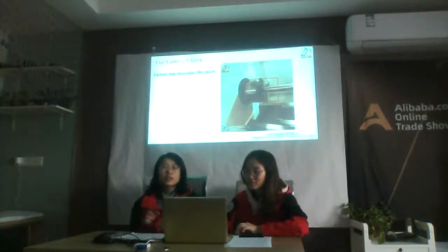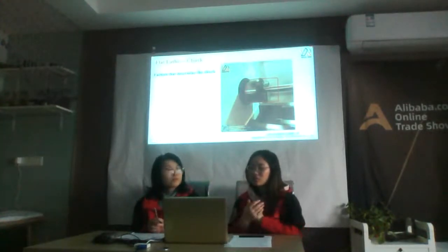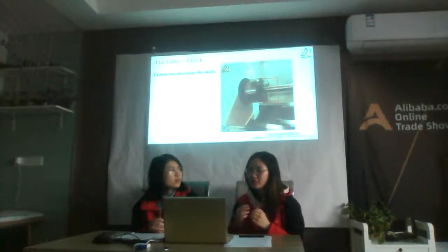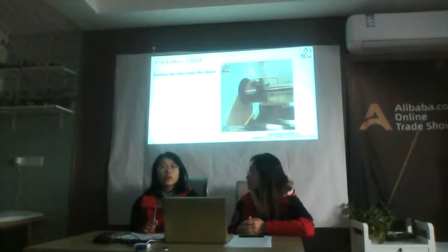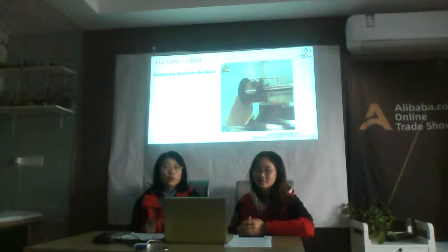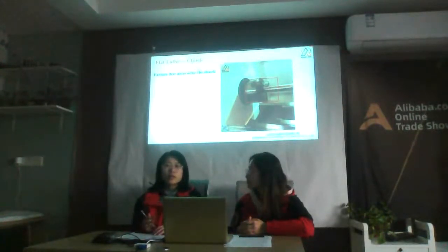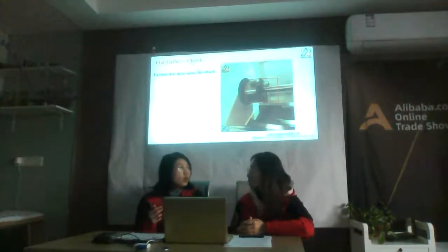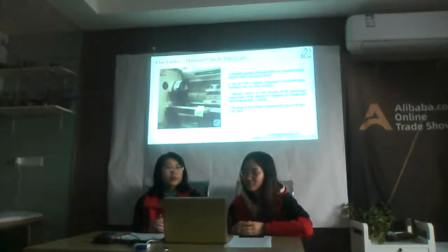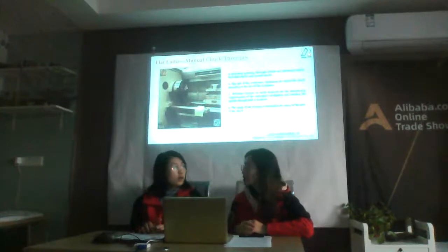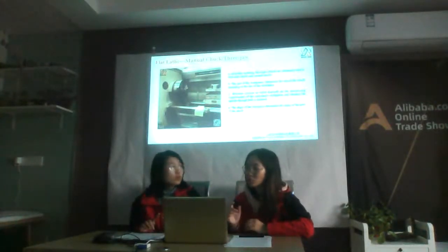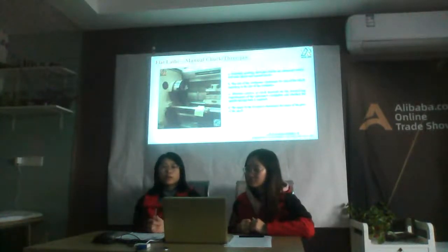And now we will introduce the CNC lathe chuck to both. How do you choose the chuck? There are four factors that determine the chuck, and we can show our boss so that our boss will be very clear and can tell our sales what chuck they need. For the first, we can see the chuck photos from here, the standard chuck of our flat bed with three jaws. Generally speaking, 3 jaw chucks are commonly used, in hydraulic chucks or manual chucks.